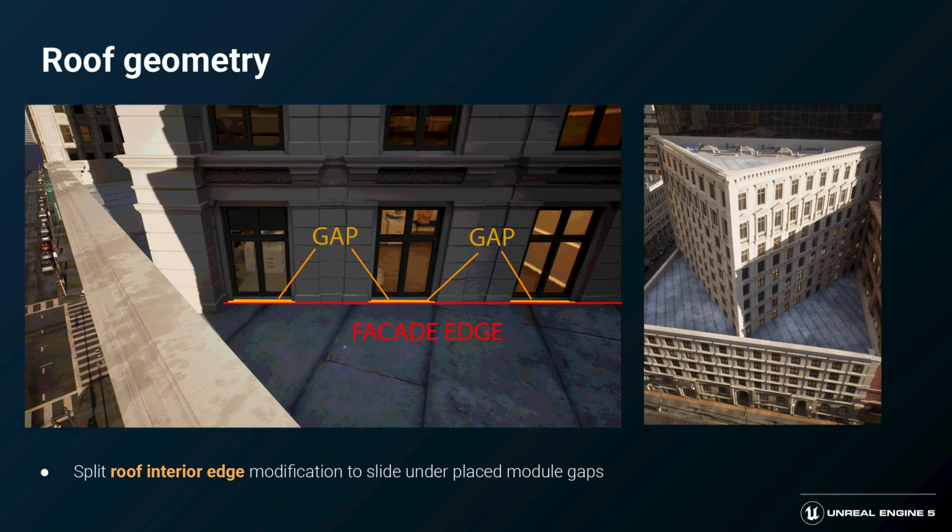Not all building modules were created equal, the biggest issue being some modules got sliced at the lower window edge, which is recessed back from the common facade plane. We had to create a function to analyze the floor slices at split roof edges and apply a push or pull inset to hide these gaps.